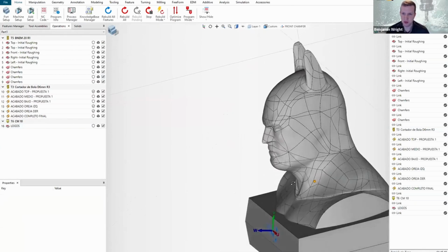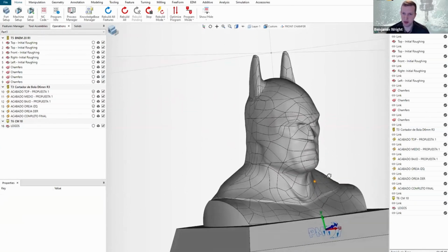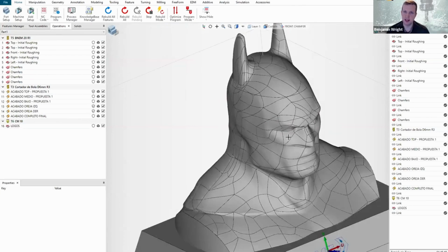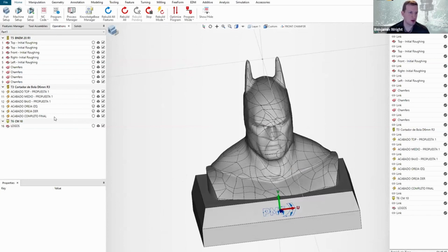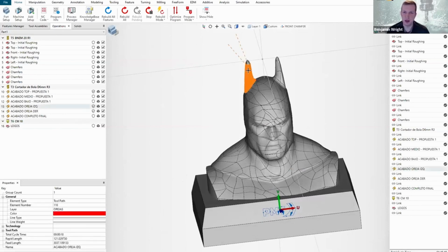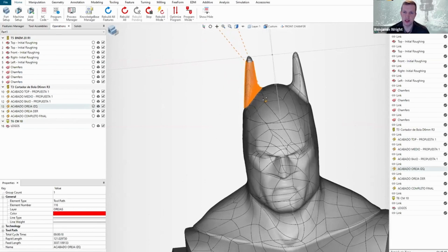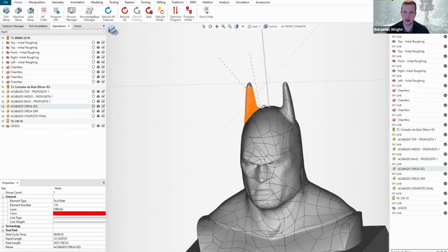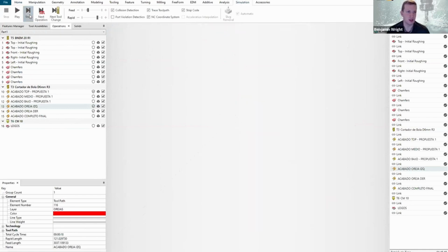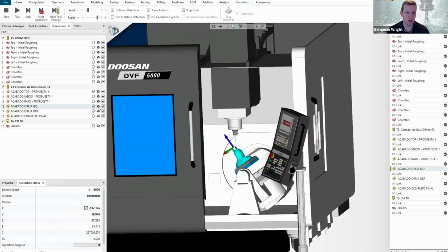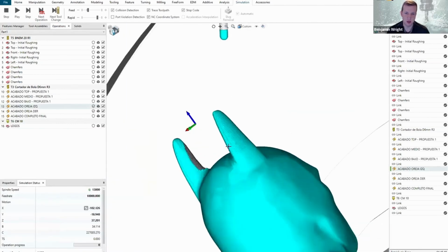And so we can take a look at this part. Lots of surfacing, lots of 3D 5-axis surfacing on this part. And because it's a fun 5-axis part, I figure we can simulate through and do something small just to get a taste of what simulation looks like on a 5-axis part in ESPRIT Edge. So with this selected, I'm going to head over to simulation, and I'm just going to single step. That way it'll get its thinking. It'll go through all the other operations up to that point and calculate the stock so that we can see that now.